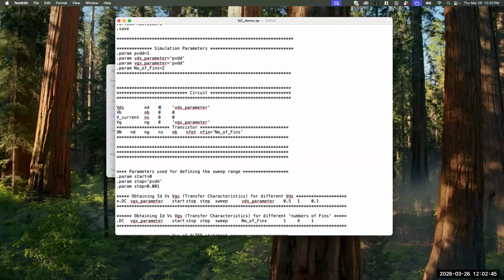Okay, notice this is a body voltage source. And I told you the reason why we are using this 0 volt voltage source here. First of all, when you connect a 0 volt voltage source between NB and ground, body is essentially ground. There is nothing between body terminal and ground. It's just literally connected. So we often use 0 volt voltage sources to connect multiple nodes, but also create the option to see the current later on. I can use this current.